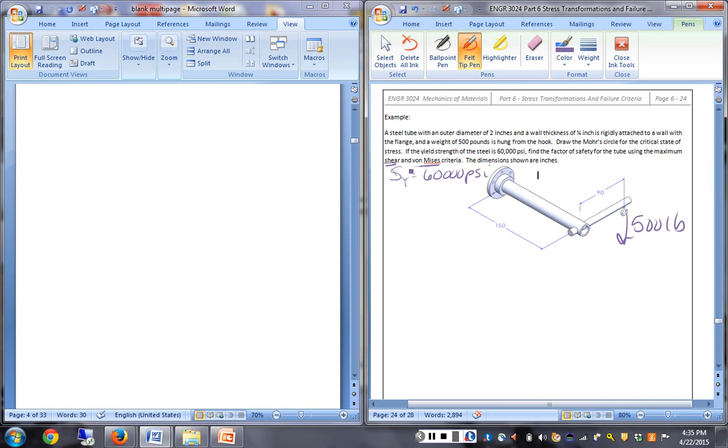Okay? What about my torsional? It's the same all the way around. So if we go this way, you've got some going this way, you got some going that way, you got underneath, and you got up. But those can't add directly with the normal stresses because those are shear stresses. We have to figure out the principals. And the shear would do what? The shear is just going downward. So basically, it's either going to be the top or the bottom.